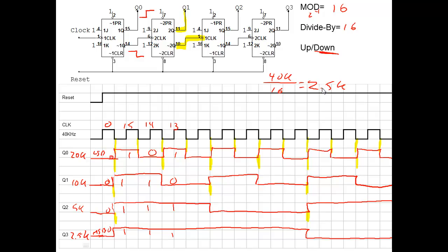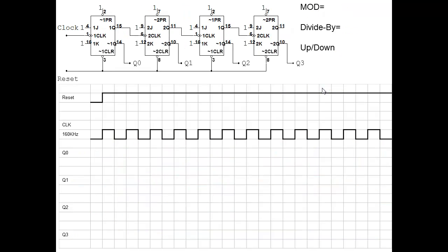Okay, one more of this type of flip-flop, or this type of counter. And this one, you'll notice the clock is still negative edge, but this time we're drawing from the Q naught. We're clocking off of Q, but we're drawing Q naught. So reset condition for these, anytime you reset a flip-flop, Q goes low, so Q naught has to go high. So we're going to start high on all these. And then the first one is just going to be negative edge, nothing weird going on there. Every negative edge we're going to toggle.